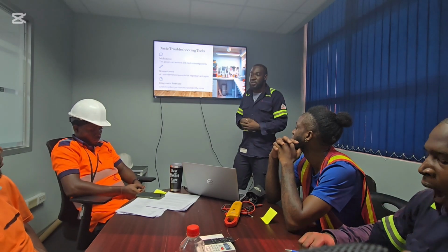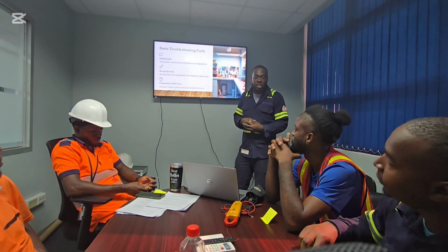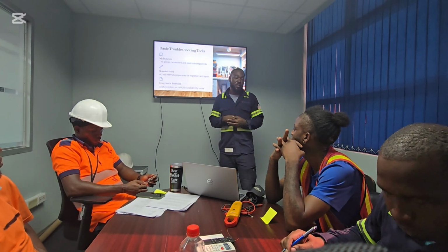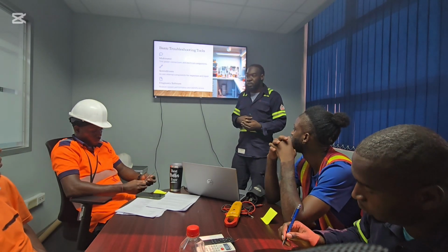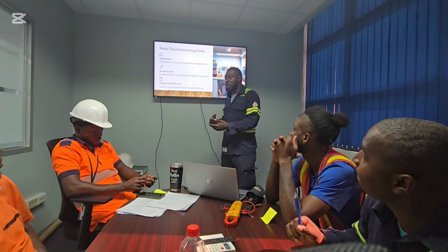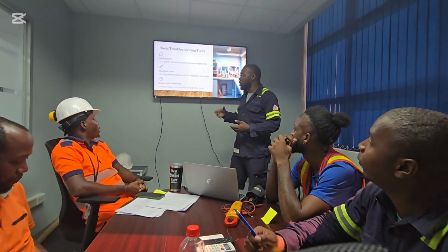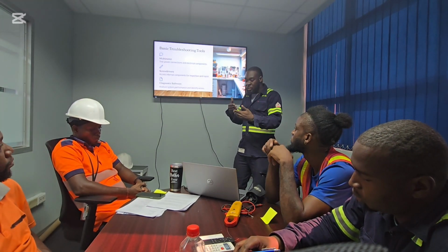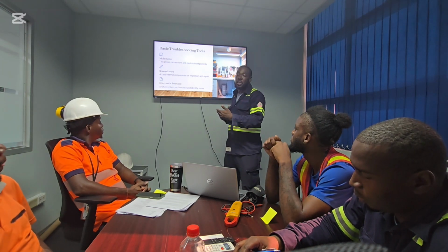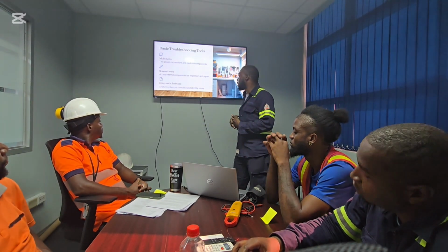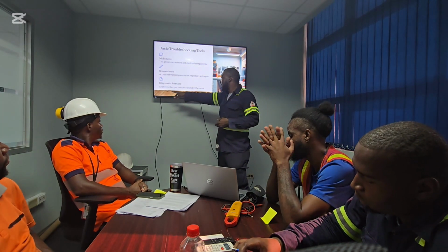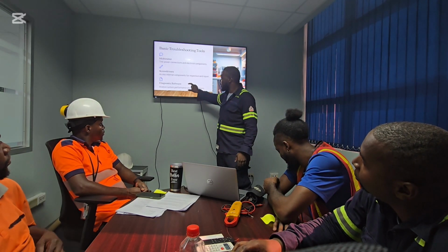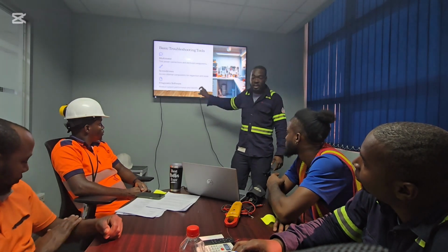Likewise, our spreaders, right? When we're having a no communication issue or a missing sensor and we're not readily able to identify those defective components, we could connect the computer and run a log check. That check would bring up all the faults on that equipment, and then we're able to isolate what is necessary and what is not, and zone in on that specific component or that section of the circuit. So it's basically analyzing system performance and identifying errors. This one is a big help in modern times.